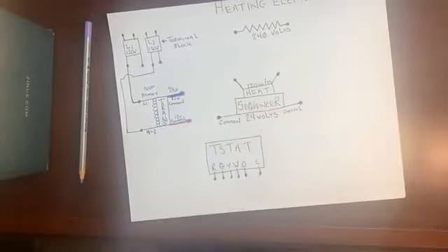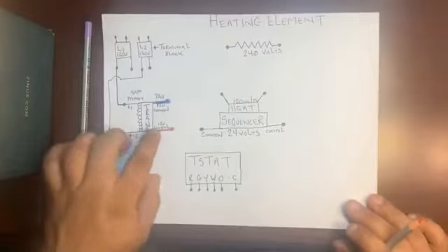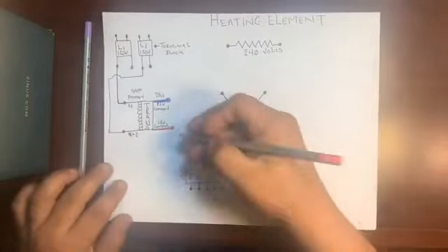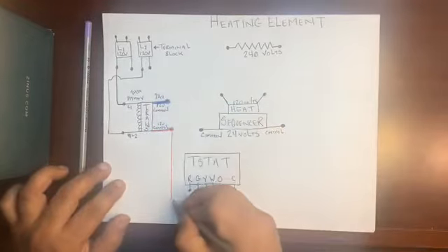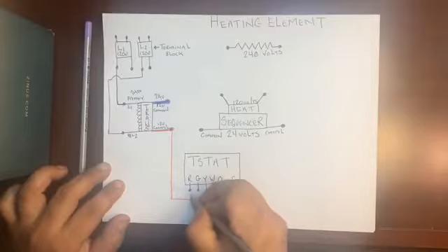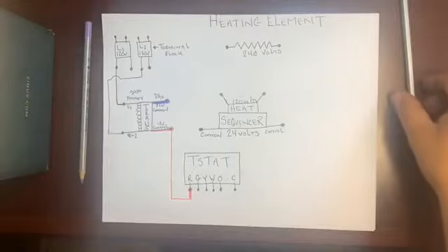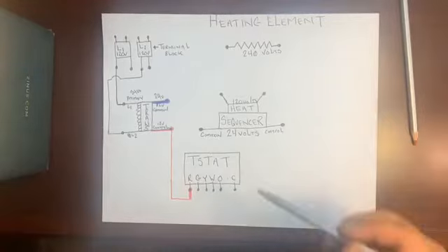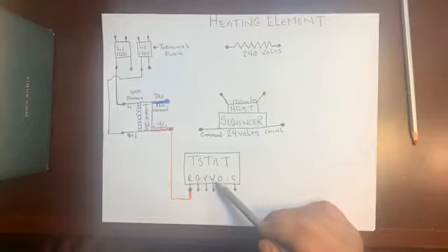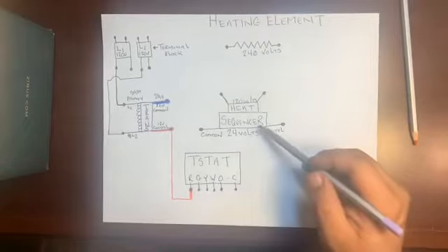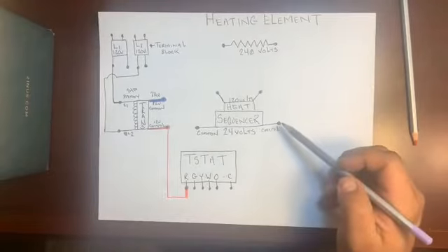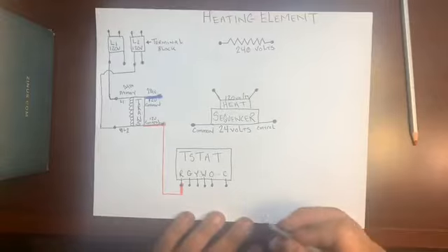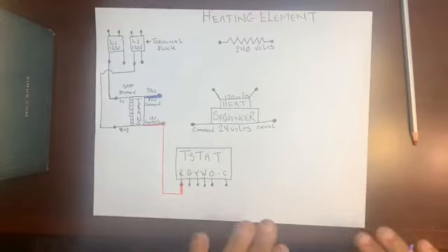Let's start with control. We agreed before that 12 volt control will only go to the red on the thermostat. So we'll go ahead and bring this down, over, and up. As we discussed in our Survey Monkeys, heat sequencer gets the white wire. The white wire goes to the heat sequencer on the other side of control to give it 12 volts of low voltage.